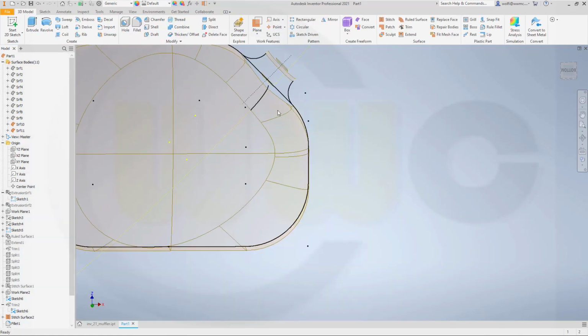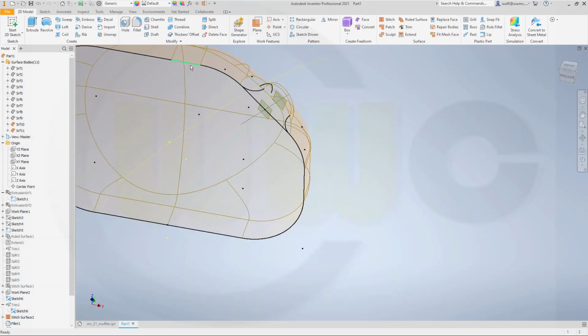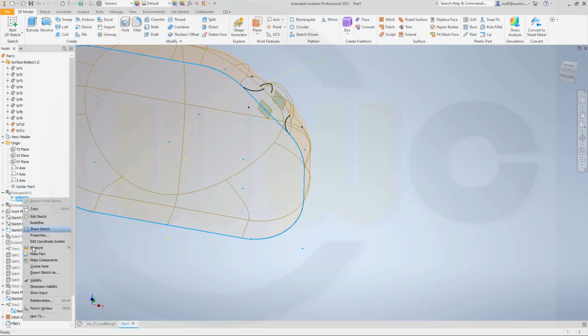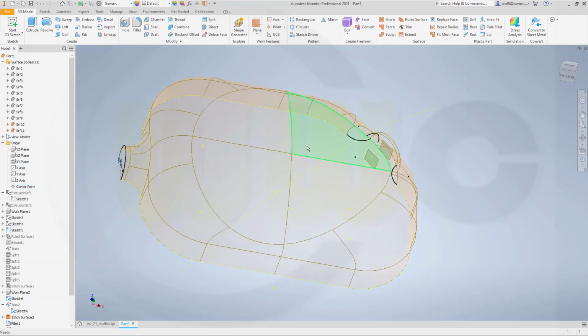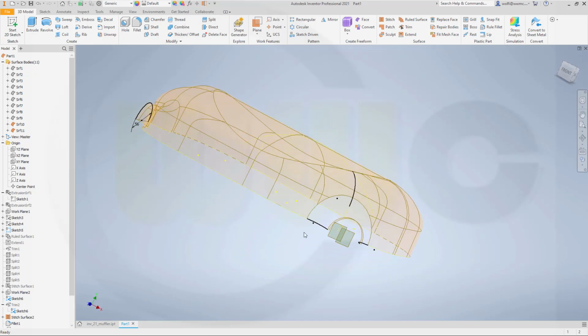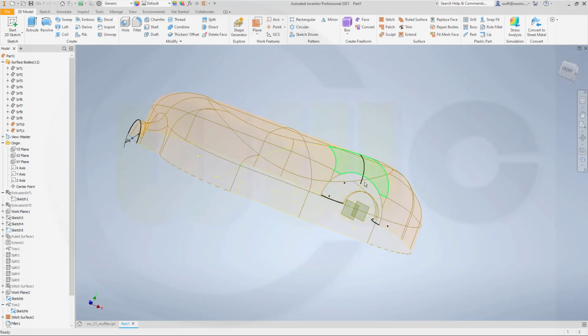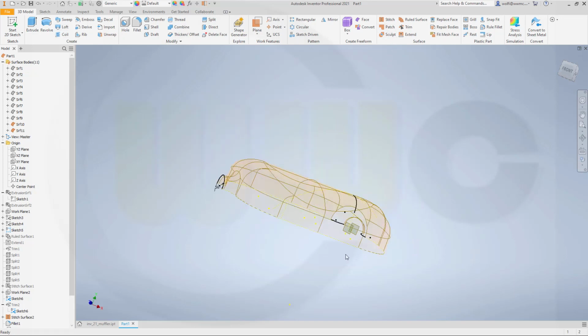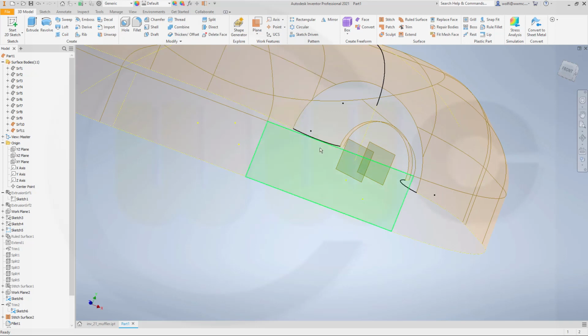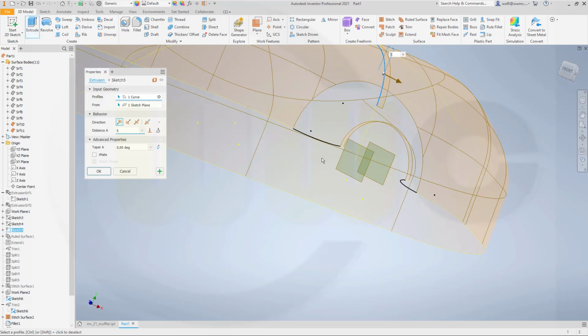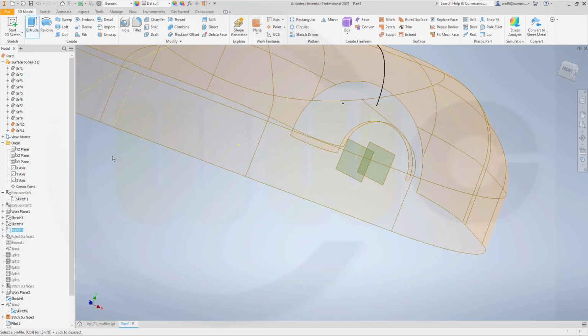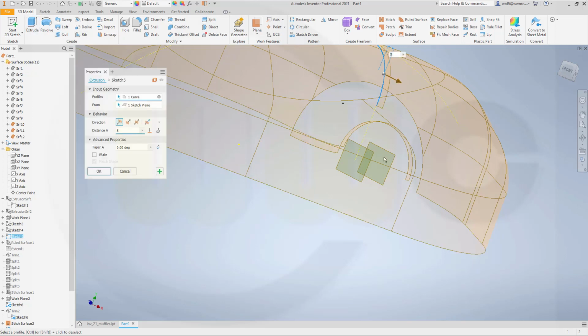Finish that sketch and hide that sketch 1. Okay. And in order to make a fill, I will need a fill surface, a patch, because the loft will not work. In order to do that, I need to extrude faces. One here, 5 mm in that direction, that's okay. And another one over there.